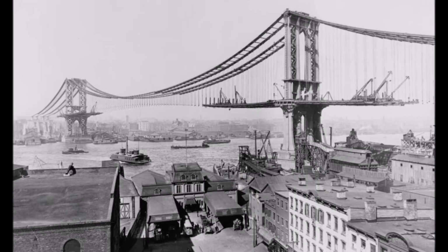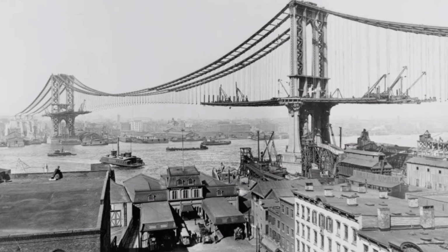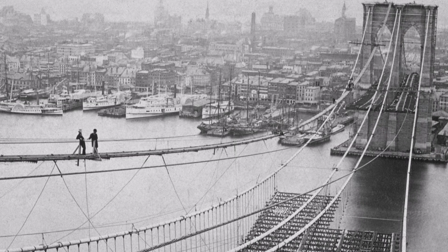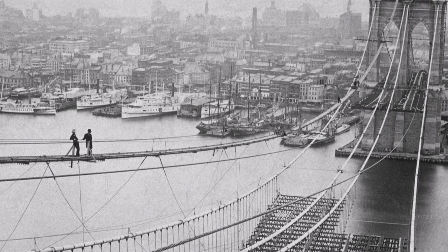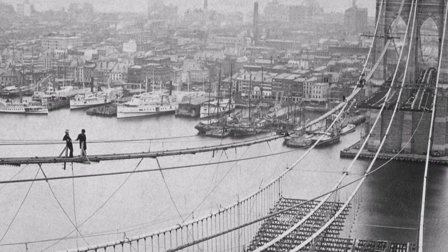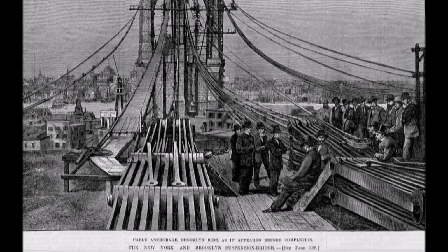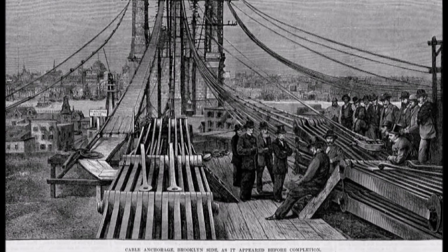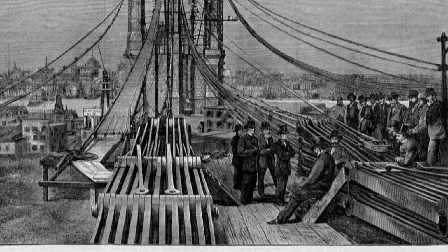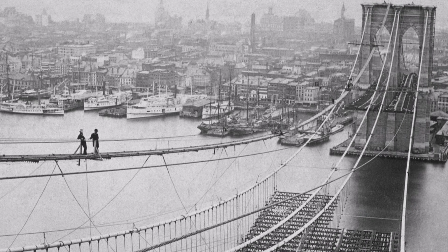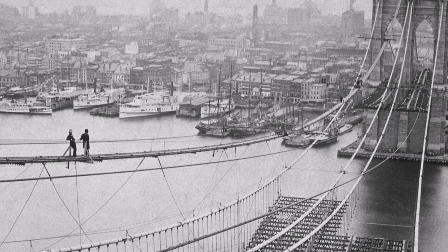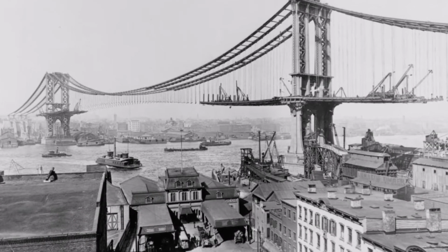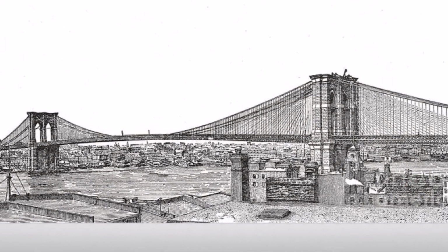The original specifications had a safety factor of 6 for any possible imperfections in the manufacture of these wire cables. Due to this defective wire, Washington then calculated that the overall factor of safety for the bridge was now at 5 instead of the original design of 6. Therefore, Washington deemed the bridge safe. Despite these setbacks, in October of 1878, the last wire cable was installed across the bridge. The decks commenced, and in 1883, the bridge construction was completed.